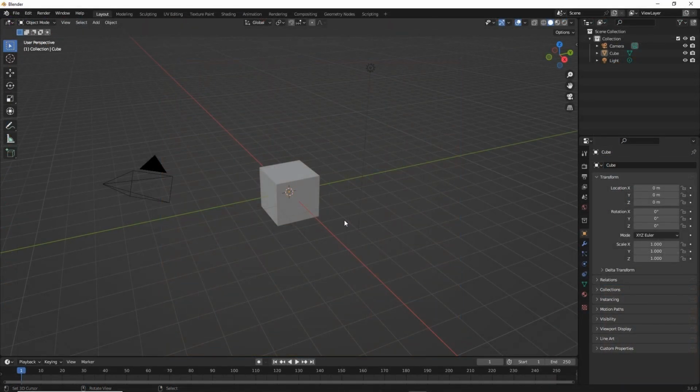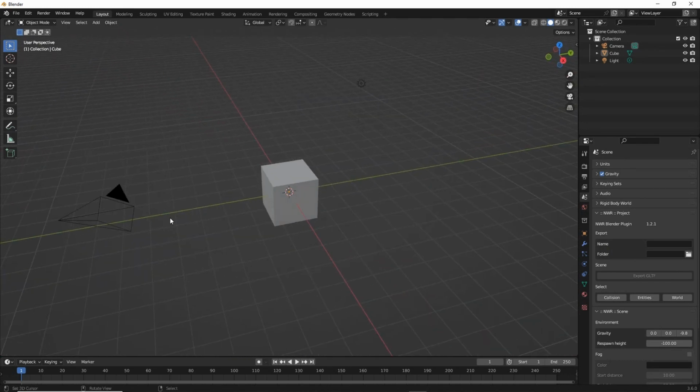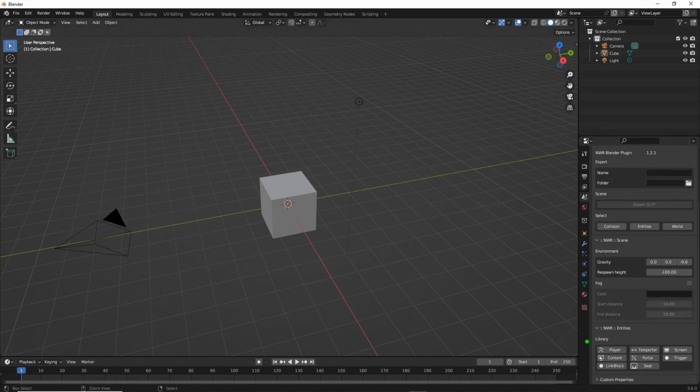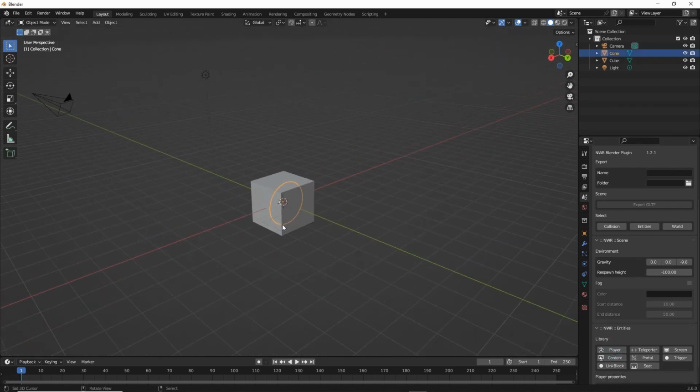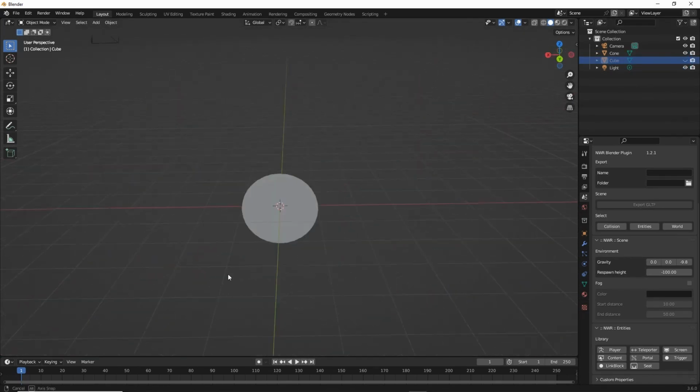So in Blender, now that we've got our Minecraft style textures made, we can start making our little level. So we'll want to switch to scene properties, and the first thing we probably want to add to the scene, aside from the cube and the light and the camera, the defaults, is from our entity options, it's the player. So if we click the button, it'll drop in a player that's obviously hidden inside the cube. So let's just hide that for the moment.